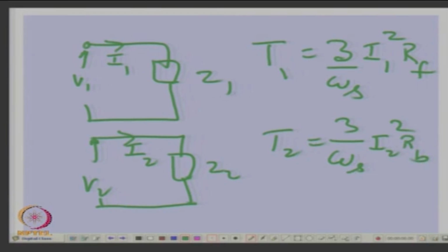You know that this is the standard positive sequence equivalent circuit and negative sequence equivalent circuit. You can also get I square R. So, net torque will be T1 minus T2. So, it is easy to solve. All you have to do in the methodology is, for a given capacitance and speed, find out V1, V2 from those expressions and find this.